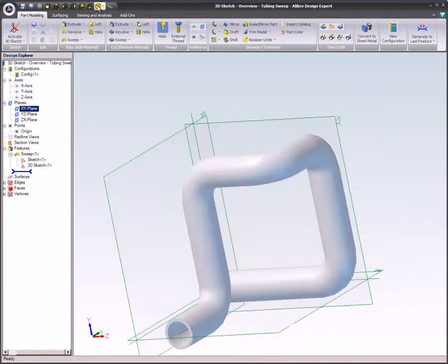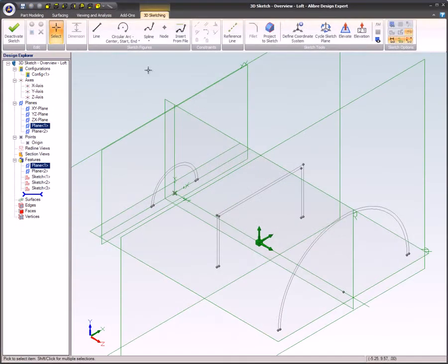And now for a 3D sketching Loft example. A loft is composed of 2 or more 2D closed sketches, each on its own plane. A 3D spline is selected from the 3D Sketch toolbar and attached to a point on each of the 2D sketches. Coincident constraints can be utilized to ensure contact with each profile sketch, but this was not required in this example because we're using endpoint nodes to attach the path to.